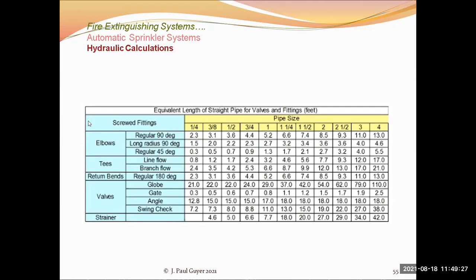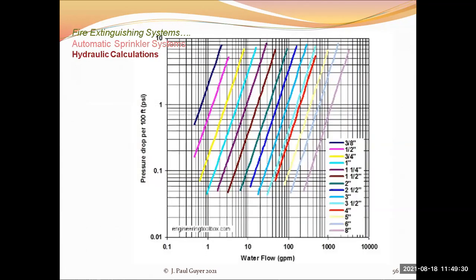And then you just use this fairly familiar figure here, commonly found in the plumbing code, that allows you to calculate the head loss at different flow rates for different size pipes. So you've got the flow rate in GPM on the horizontal axis, the pressure drop for the different sizes of pipes that you see there. And you just use a simple little figure like this to calculate the pressure drop between where the water enters the building and that most remote